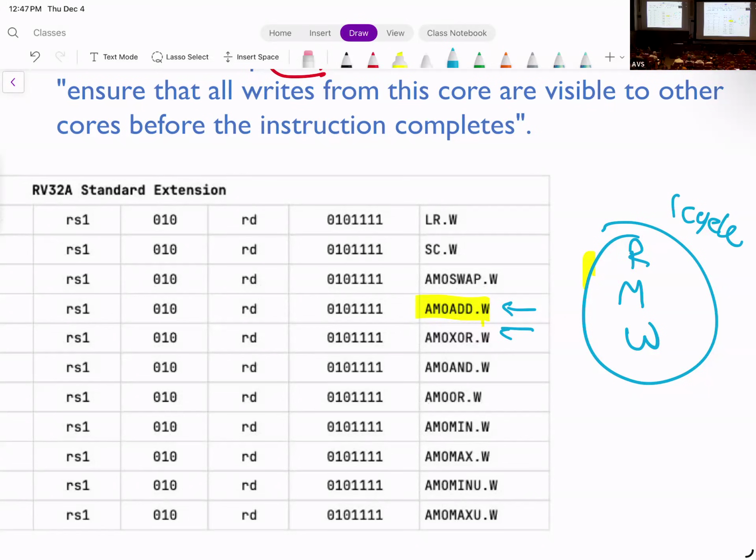Yes, it will be supported by RISC-V processors. I mean, you have to check your processor to see if it's supported, because this is not part of the base. Not all RISC-V processors support this. You have to actually bake this into the hardware. But if your hardware supports this, then yeah, at the software level, you can just write AMO add R1, R2, and then move on. Okay?